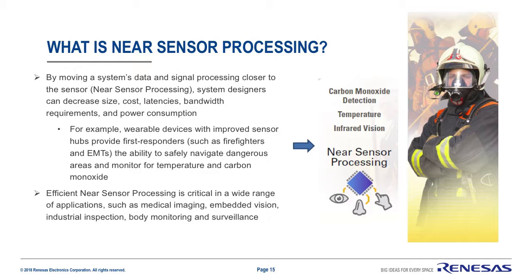An alternate method is to take average samples and only report back key environmental changes to the monitoring center. Some events are more critical than others. For example, do we need to report temperature once per second? So if we can sample data, process and average the data, reject outlying data points due to noise or interference, and then send a concentrated but succinct data set, we're better off.